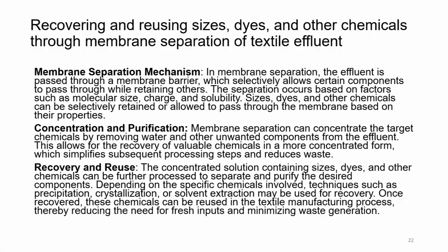Recovery and reuse. The concentrated solution containing sizes, dyes and other chemicals can be further processed to separate and purify the desired components. Depending on the specific chemical involved, techniques such as precipitation, crystallization or solvent extraction may be used for recovery. Once recovered, these chemicals can be reused in the textile manufacturing processes, thereby reducing the need for fresh inputs and minimizing waste generation.